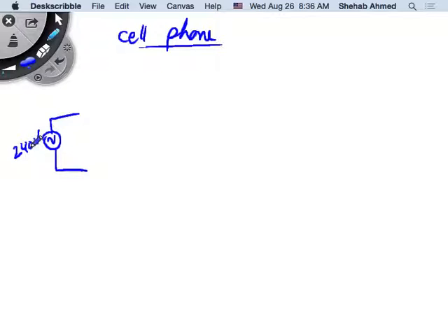RMS, average? RMS, right? So we know that anytime you talk about voltages, it will typically be RMS. In single phase systems, it will typically be RMS. But if you are talking about a power system, not single phase, if somebody doesn't specifically say single phase, then they're probably talking about three phase, and they're talking about line to line voltage RMS. That's typically what they're talking about. If they are specifically talking about single phase, it's going to be single phase RMS, of course.